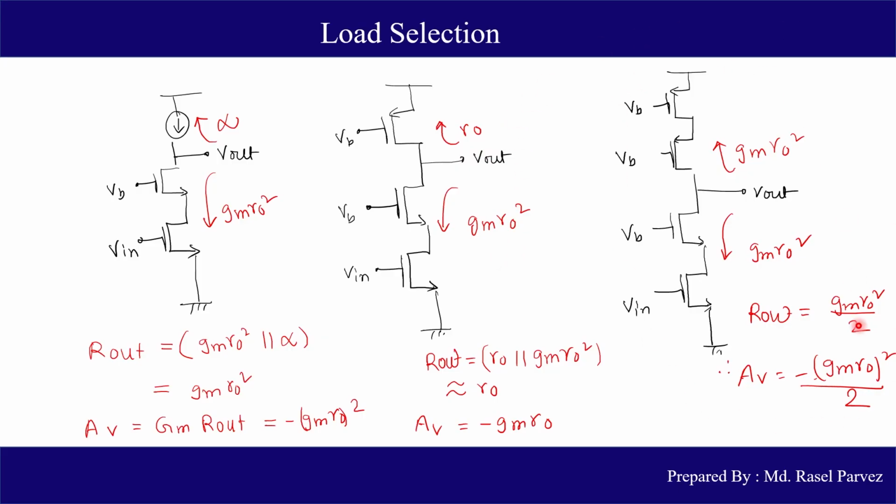So this is the final circuit. We have used 2 PMOS as loads, and this is the previous configuration. So the upward branch and the downward branch have equal resistance, so the Rout will be something like this. It will not significantly drop like that. Then we will have a significant gain value like this.